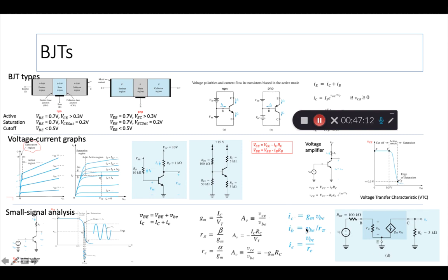One last thing I'll point out, two things. One, the voltage gain, right? That's a very important part of why we study transistor circuits. The voltage gain is defined as many things. Actually, there's a lot of formulas. The first important formula is the change in output voltage by change in input voltage is the voltage gain, right? That is pretty easy to follow. But it also can be derived directly from such things as the I_C R_C and the V_T. It also is connected to g_m.